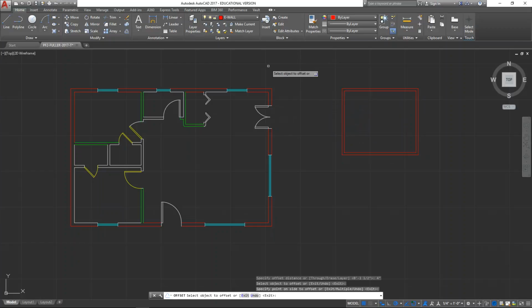So just a little shed, not that big, and of course, my normal thing here with the offsetting, 4 inches inside. Okay, and then let's say there is going to be an interior wall inside of there, so select I wall, and however I want to do my interior wall, I'm going to explode that and offset, and we're going to make this interior wall 3 feet.